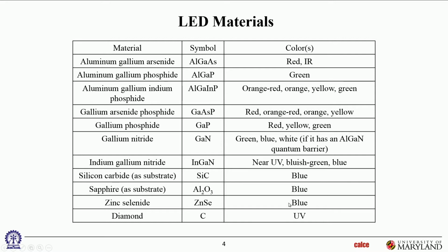This one I don't fully understand, so I'm going to skip over it, because there are other technologies to produce white light that are usually used commercially. This one is not used that much commercially, but apparently there's a combination of gallium nitride and aluminum gallium nitride, a particular technology that provides white light, but that's usually not how commercial white light LEDs do it. They do it differently.